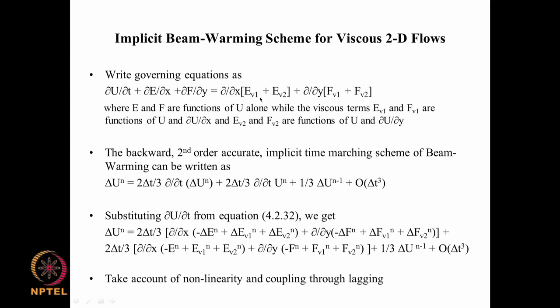So, in that sense it is just the same equation, but written in a special way, because we need to evaluate cross derivatives in a certain way and normal derivatives in a certain way, as we have seen for McCormack's scheme. So, the same idea is being brought into this. Having written this, how do we make up a solution scheme, which is the Beam-Warming scheme?